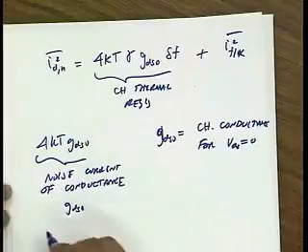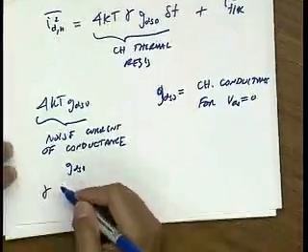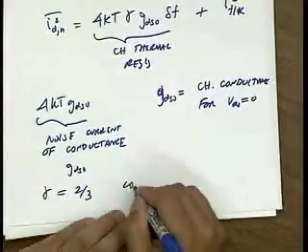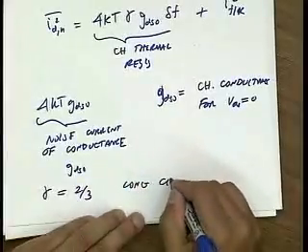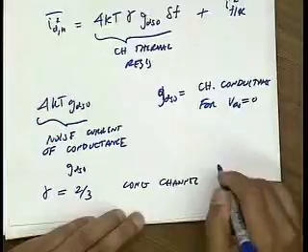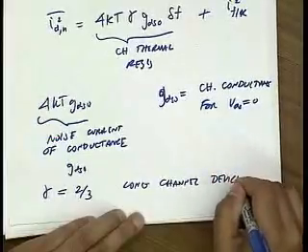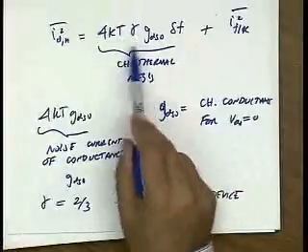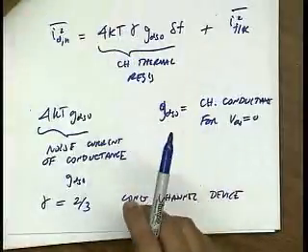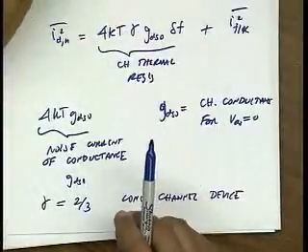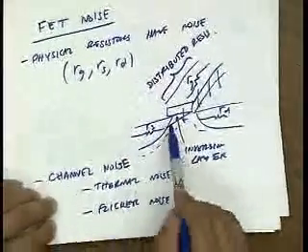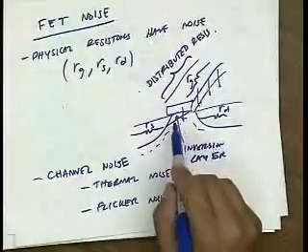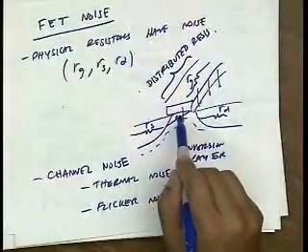Now, unfortunately, there's this term gamma. And for a long channel transistor, it's equal to 2/3. In some ways, gamma is the correction that takes into account that the channel is not uniform. And the way you calculate gamma, if you guys are into this, you can go home and try this, is you break the channel up into small little pieces.